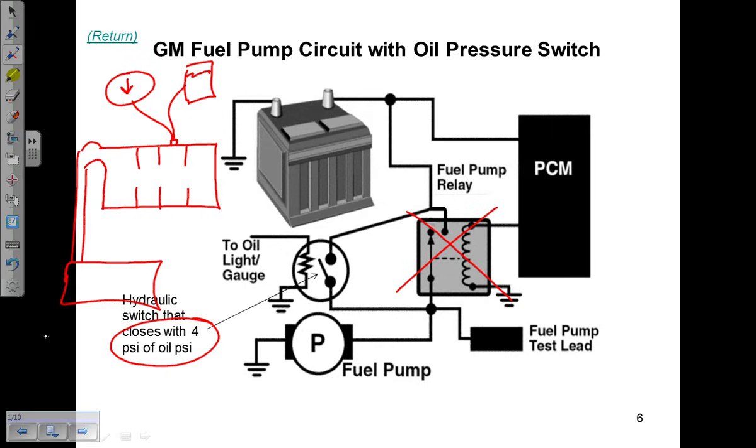What that means is when you put this pressurized container, and when we try to run the car off of this instead of the pump, you're going to push all that solution either back on the pressure line or back on the return line, so your regulator being here, back on the return line, and you're not going to be able to clean the injectors like you're supposed to. It's going to push that solution back to the tank. Okay, so it's a bleed down problem.